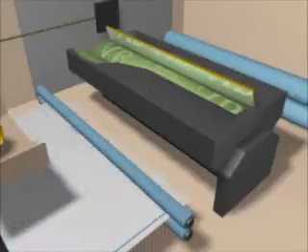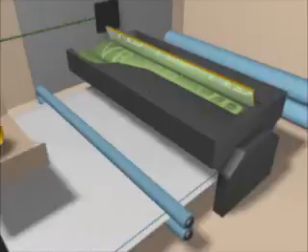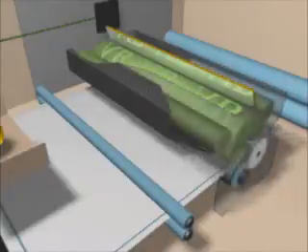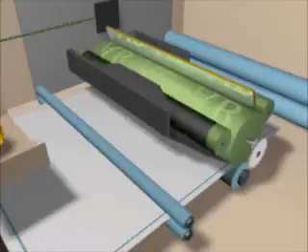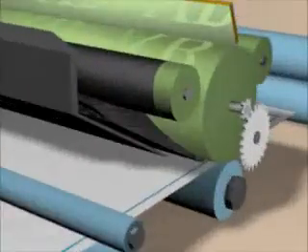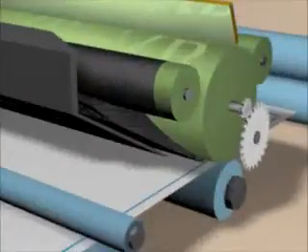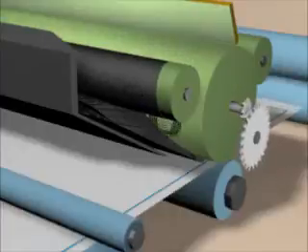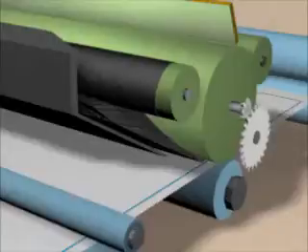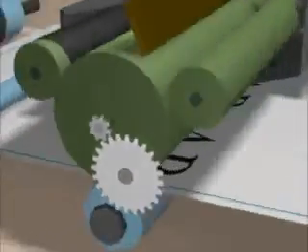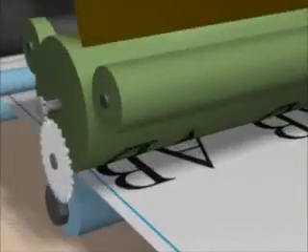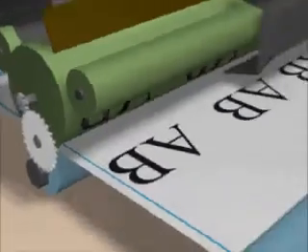Meanwhile, a sheet of paper is pulled into the printer. It passes between two rollers that give it a static charge of its own, exactly the same as that created by the laser, only stronger. As the drum rotates, it passes a bin containing a black powder called toner. The toner too has an electrical charge, but it is the opposite of that on the print drum. Since opposite charges attract, the powder sticks to the drum wherever the laser has charged a dot.